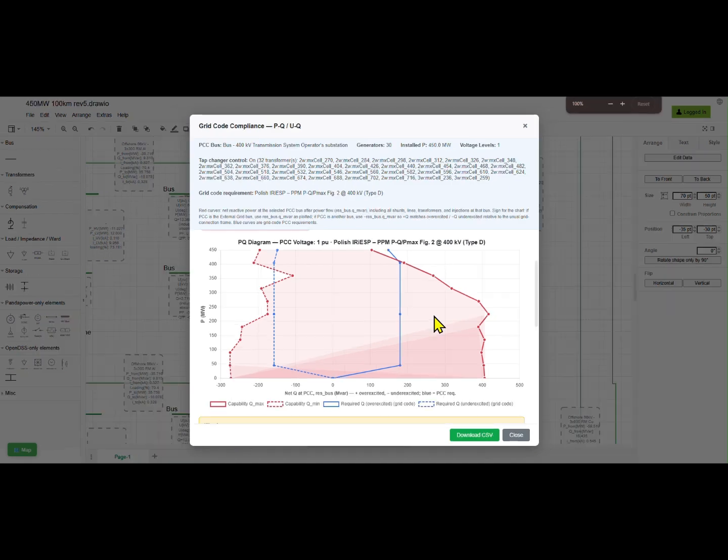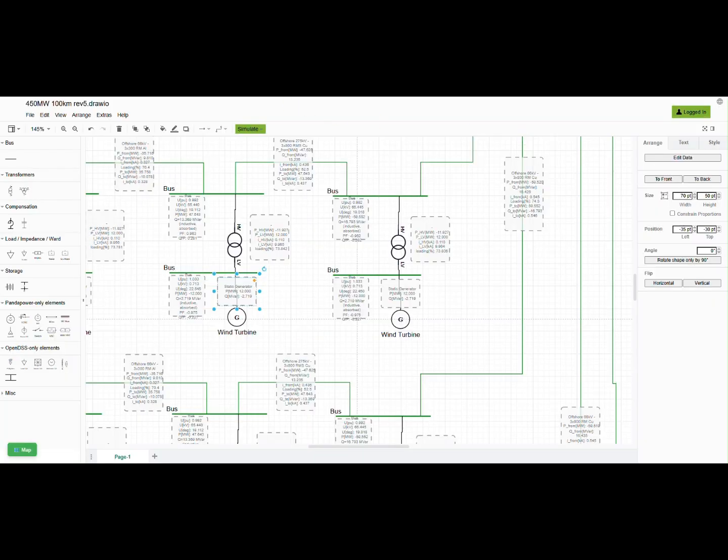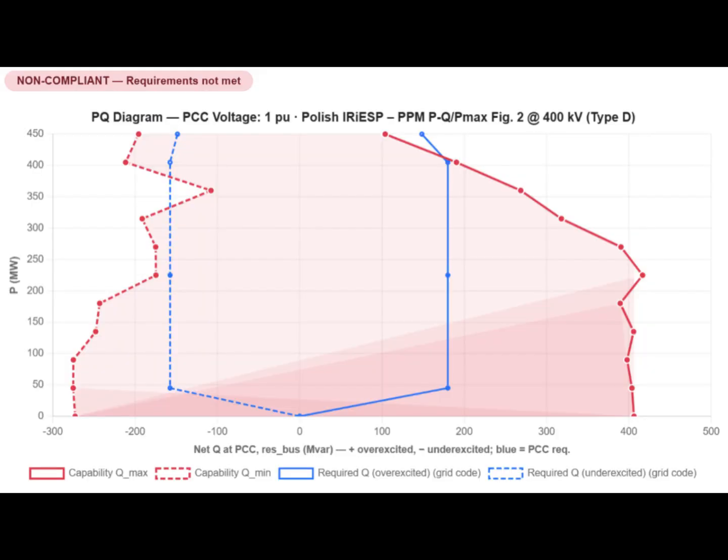The engine wanted to use the full minus 14.5 MVAR. It tried it first, but the power flow failed to converge, so it backed off down a fixed ladder until it found a fraction that solved, and that was 0.5. So the minus 14.5 MVAR per unit would widen the underexcited boundary. It simply wasn't usable because the deterministic Newton-Raphson solve diverged there.